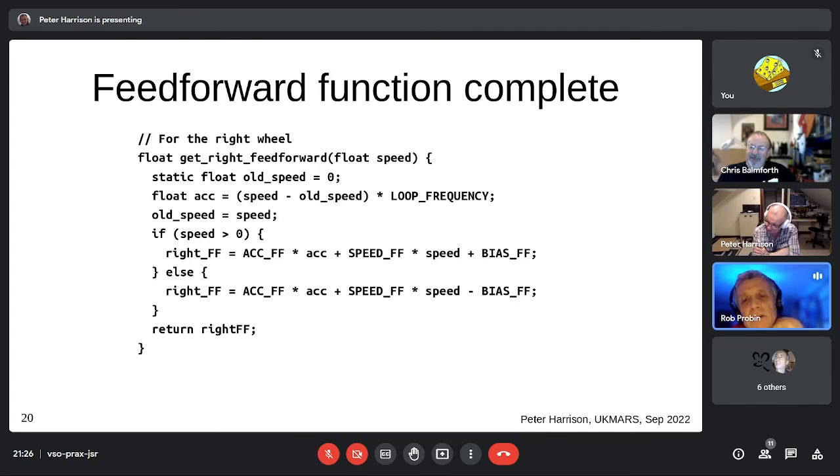Yeah, I mean, I guess feed forward works because you can either anticipate the load or you've got a constant load. I mean, if you've got a load that you can't predict, then you've got to use feedback to control the system. But obviously, with most of these robots, the mass is fixed. We're running on a surface that's reasonably the same friction across it. It's reasonably level. So it's mostly a predictable problem.